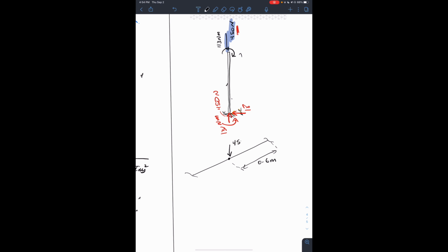So we have the 450, which balances out this force here. We have a force in the equal and opposite direction of 80 newtons. It balances out this force here. And then our reaction moment, here it was anti-clockwise, so therefore here it will be clockwise, which is 131 newton meter. So this is our loading on beam 3.